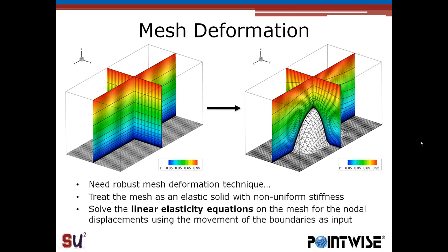I think earlier for the ONERA M6 wing, that large deformation of the tip section, we can go ahead and compute that. And that works just fine. We've also put in some other things for robustness. For instance, we found that if we sometimes break these large deformations into increments, so in the config file we call these nonlinear iterations of the linear elasticity problem.